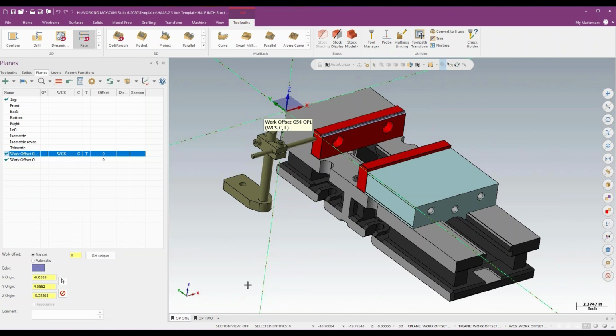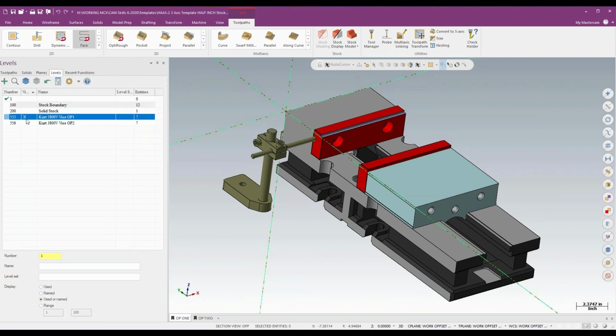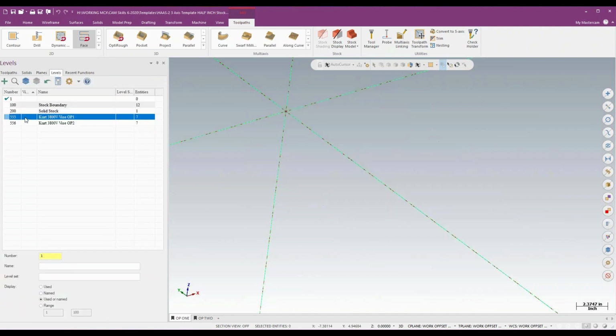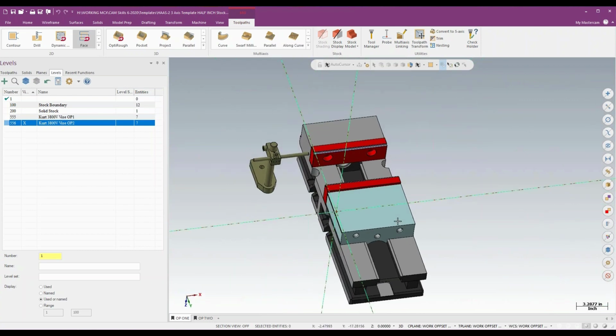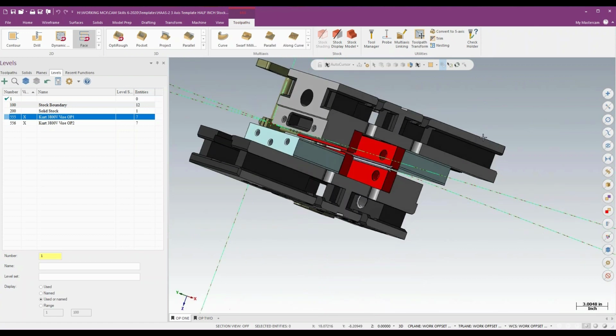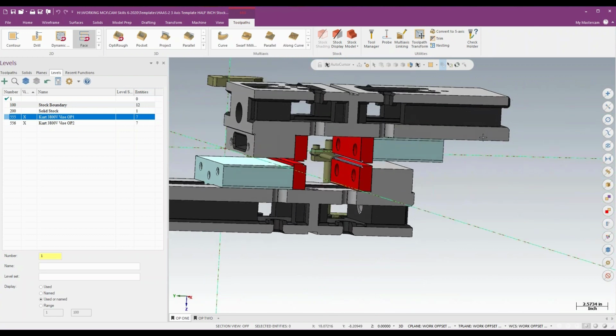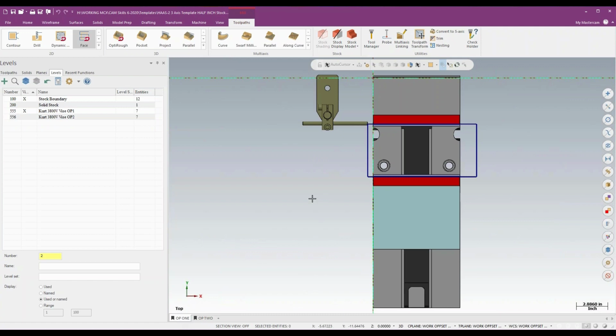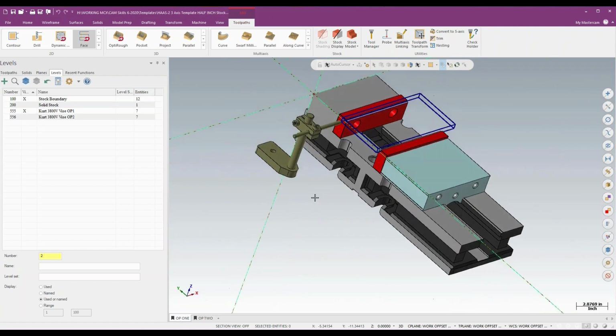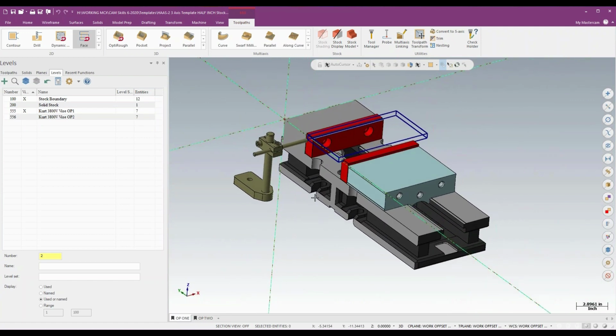This is just the idea of dropping in and setting up very quick templates, right? The other thing I have on here is a second vise for the flip, which is really just the same vise. If I turn them both on, I'm using the sandwich board method, so I can suspend a part between two vises. I've also got a couple of quick view sheets set up down at the bottom. If you guys aren't using view sheets, I highly recommend you start looking into them, especially if you're doing multiple setups.